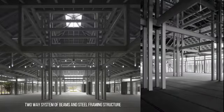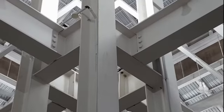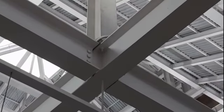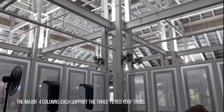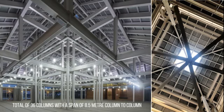The overall Masjid Cyberjaya 10 Mosque is built using a two-way system of beams and steel framing structure, making it open and spacious. The fundamental component of the praying hall is composed of a universal column measuring 200 x 200 mm and an I-beam measuring 300 x 400 mm. The major four cores in the center are made up of four columns each to support the three-tiered roof truss. There is a total of 36 columns with a span of 8.5 meters column to column.